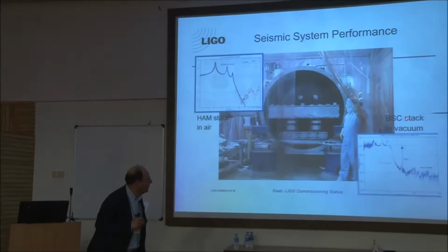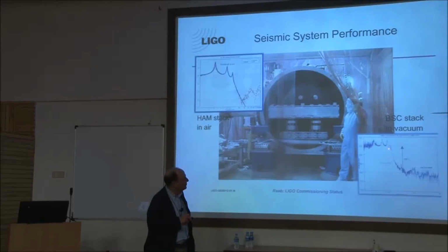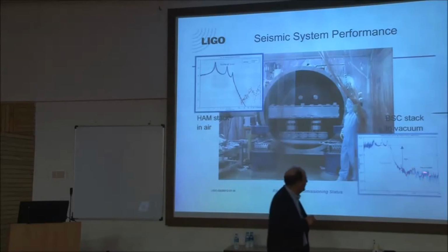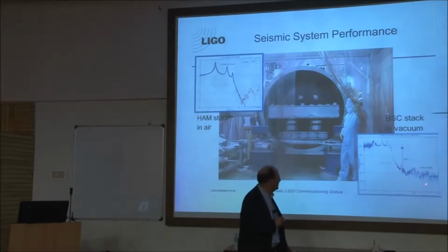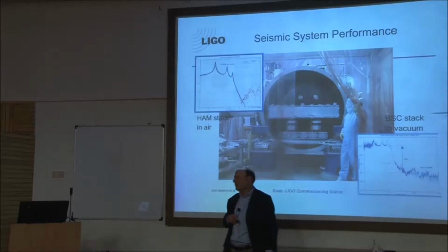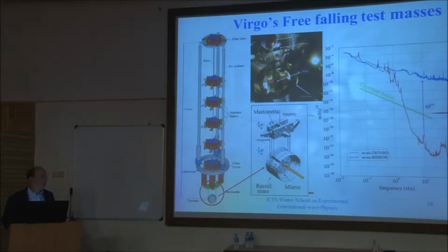Here is a measurement of the frequency response of the isolation stack that I was showing you before, the one that goes in the more critical systems. Here is 1, 2, 3, 4 peaks, a really steep frequency response, and then no proof that we had anything more than the internal resonance effect. But we've got a number of orders of magnitude before it levels off. So this is a really successful isolation system. This is giving us good isolation by around 30 hertz. Okay. So we had 6 orders of magnitude by that measurement in the LIGO stack. And that's enough to have hit our target.